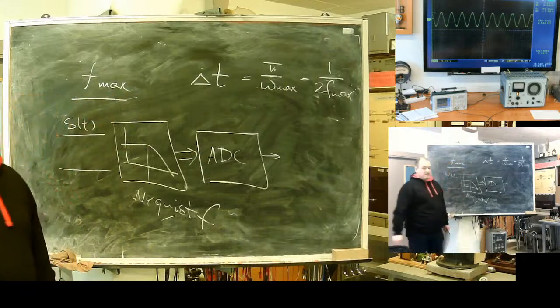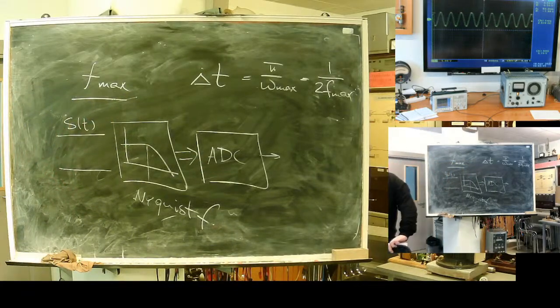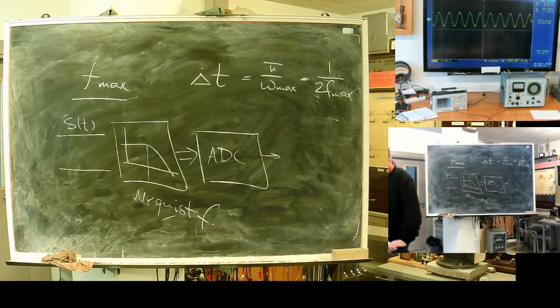And on the other hand, the Nyquist frequency sets for you what? Basic, let's say baseline requirements for your system performance. If you want to record, for example, some sound with frequency up to 15 kilohertz, what? You need a sampling rate of 30 kilohertz. Actually, for sound, it's 44 kilohertz for good quality.